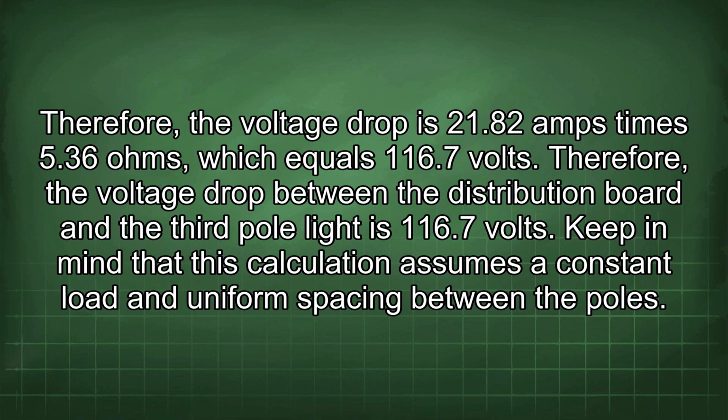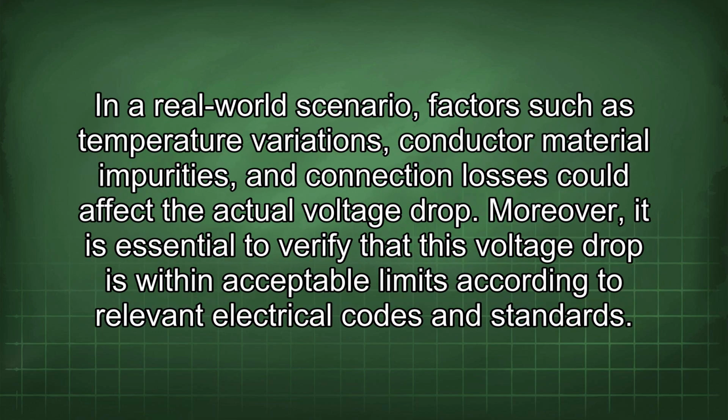Keep in mind that this calculation assumes a constant load and uniform spacing between the poles. In a real-world scenario, factors such as temperature variations, conductor material impurities, and connection losses could affect the actual voltage drop. Moreover, it is essential to verify that this voltage drop is within acceptable limits according to relevant electrical codes